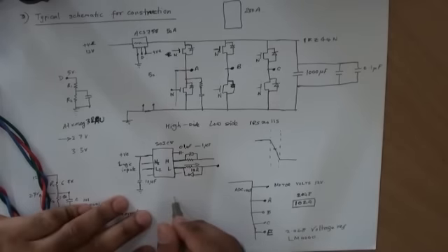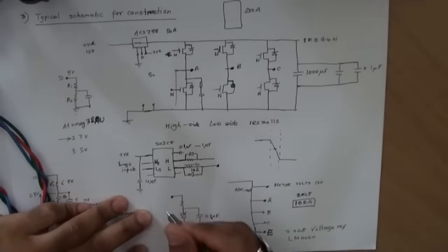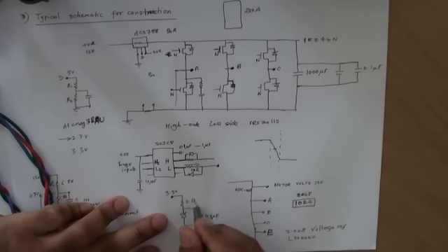Basically they're wired up like this, and again, don't forget the filter capacitor. I'm sorry, this would be your 3.3 volts, and typically a 2.2k resistor, and over here you're expecting 2.048 volts.